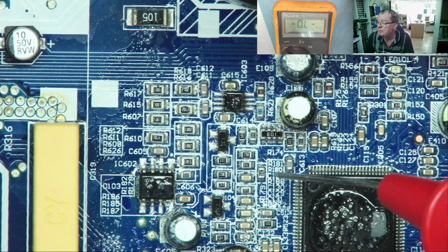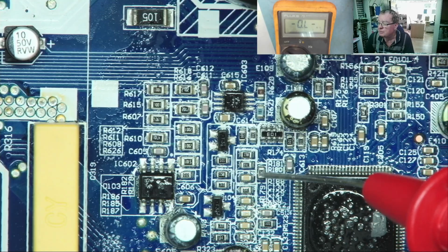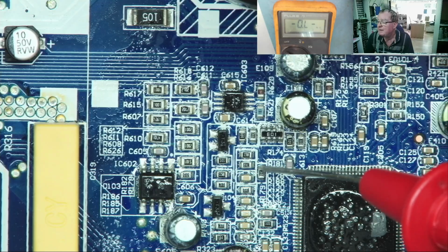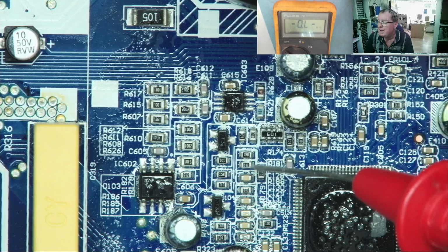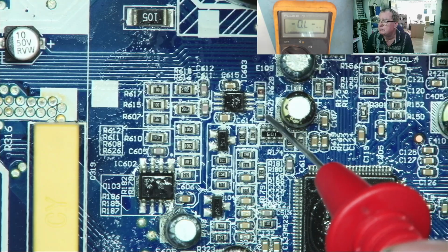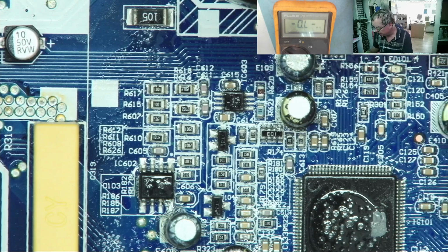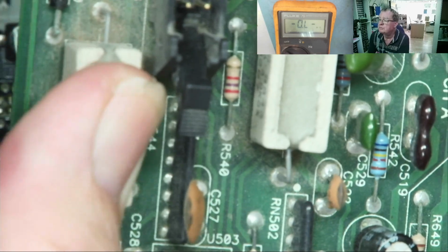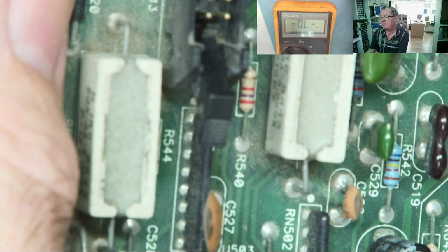The only ones which are a bit more difficult are the ones like these, 01C. I normally look these up because I'm not familiar with them. And it's not quite so easy to learn that system. You'll probably get used to certain values after a little while. These are close tolerance resistors, okay, 1%. And you have to look these codes up probably. Look, one there, 183, not 183 ohms, 18 and 3 zeros, 18,000. And the same applies, of course, to resistors with color codes. Go and learn the color code system, guys. It will save you so much time, okay?